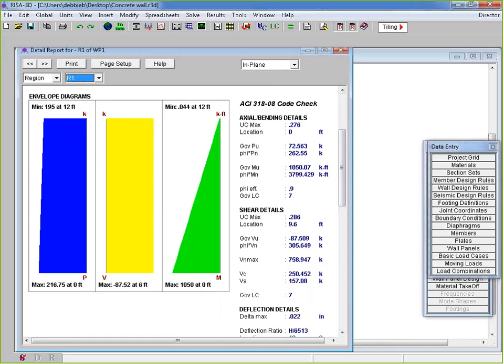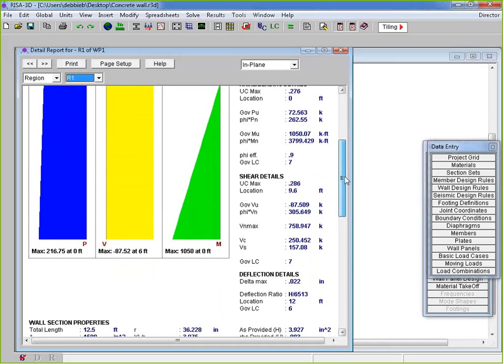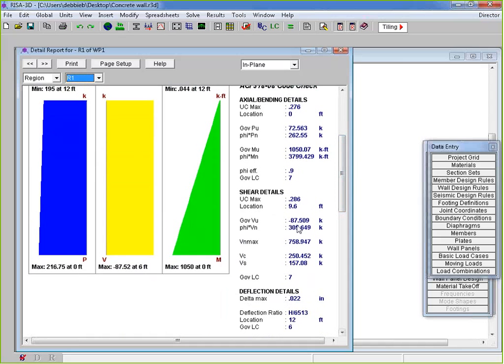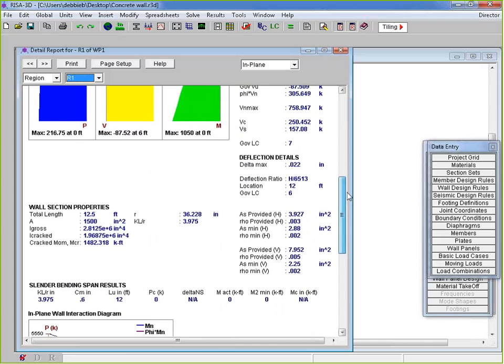And if we look down below that, we can see here that our actual moment and our shear here is listed out actually the same load combination for our model, which is because it's a pretty simple model. So if we're seeing another governing shear there, load combination 7. And as we scroll down below that, we can see here the deflection. So this is an interesting thing here.